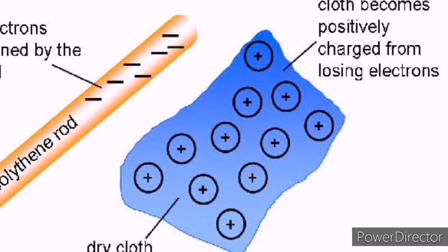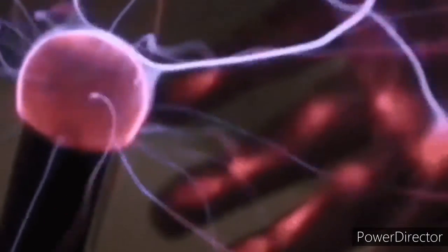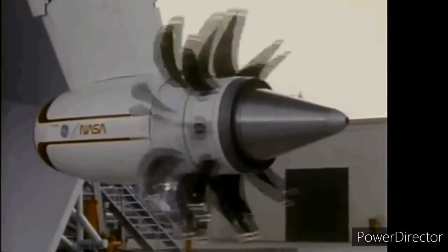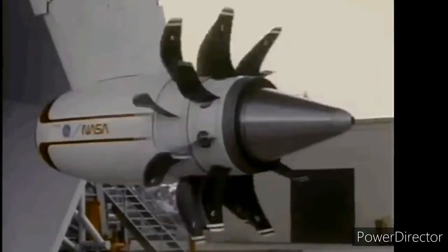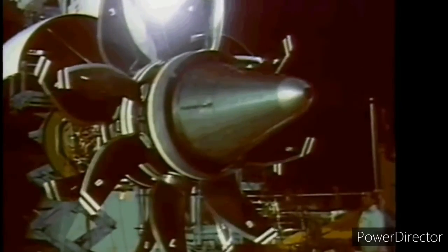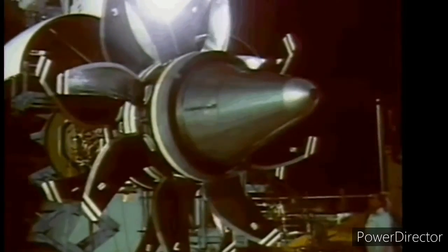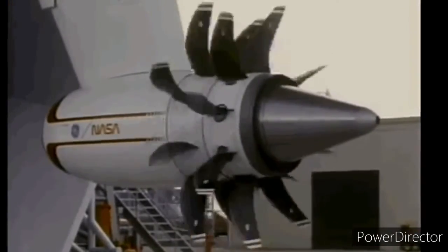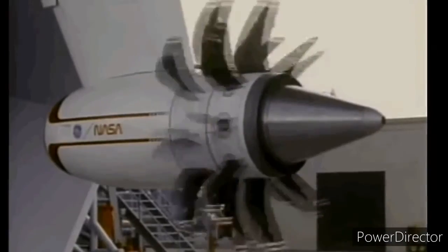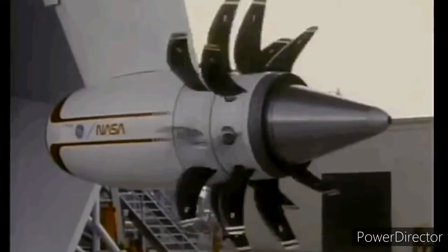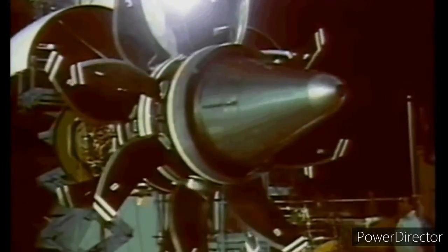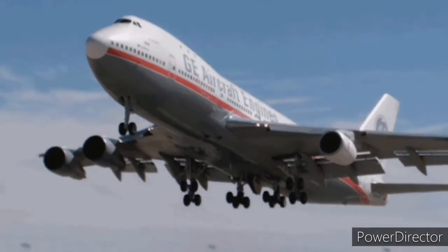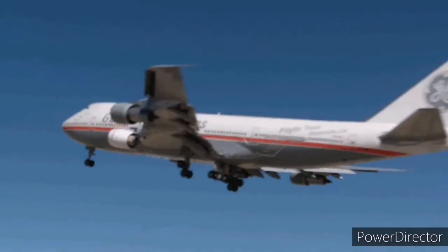Dangers of static electricity. Filling fuel on a plane can be very dangerous. A lot of friction is applied as fuel goes through the hose, meaning the hose becomes charged. This could lead to a spark and then an explosion. To prevent this from happening, grounding and earthing is used, with wires that are lined with metal, which allows the charge to be conducted away.